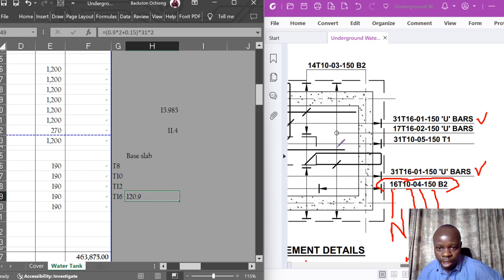So you follow it again, then the perpendicular bar to it, you can notice there is a difference in thickness of the arrow and also the reinforcement bar. So like in this case, this particular arrow is just for annotation, but then the reinforcement bar itself is perpendicular to it.